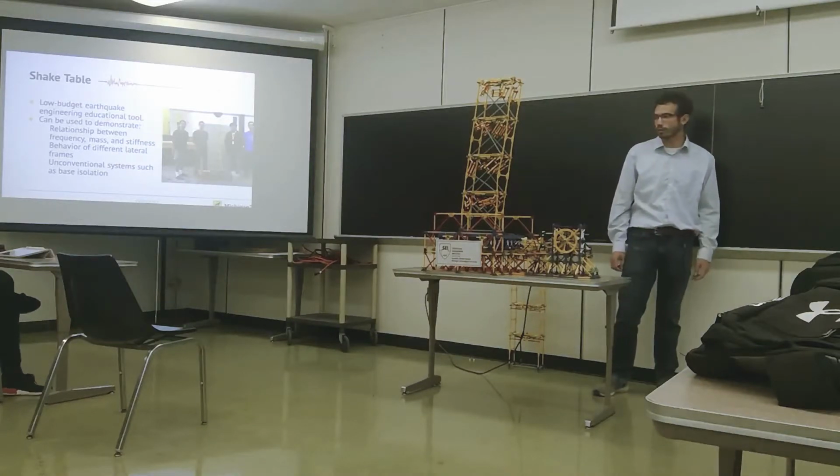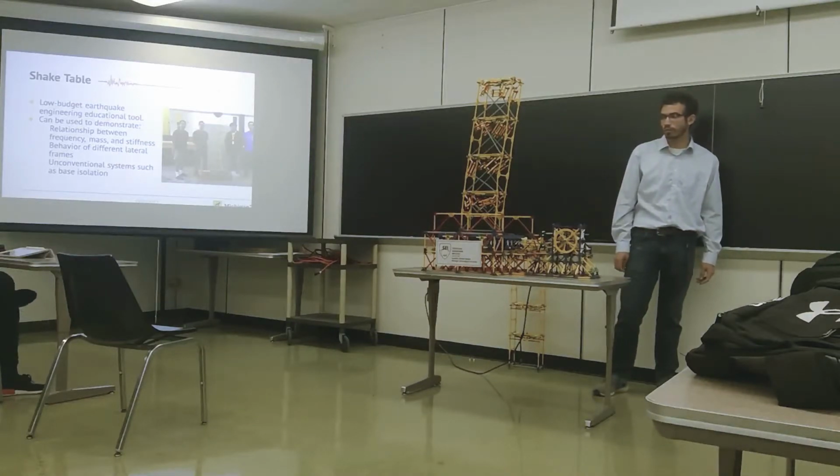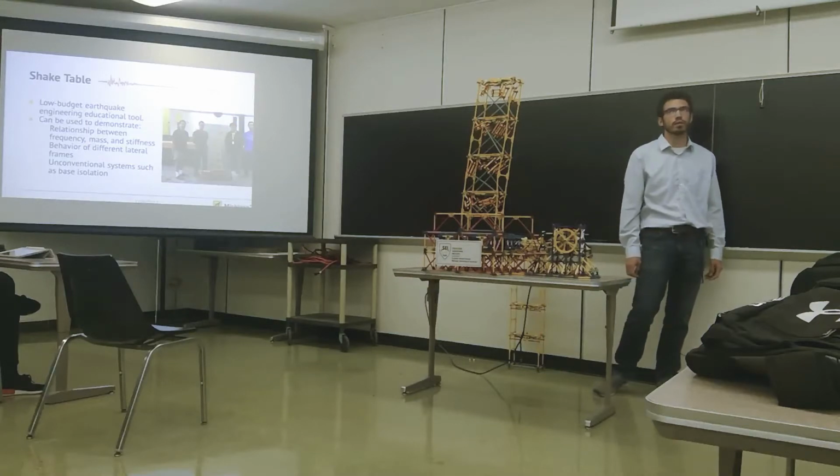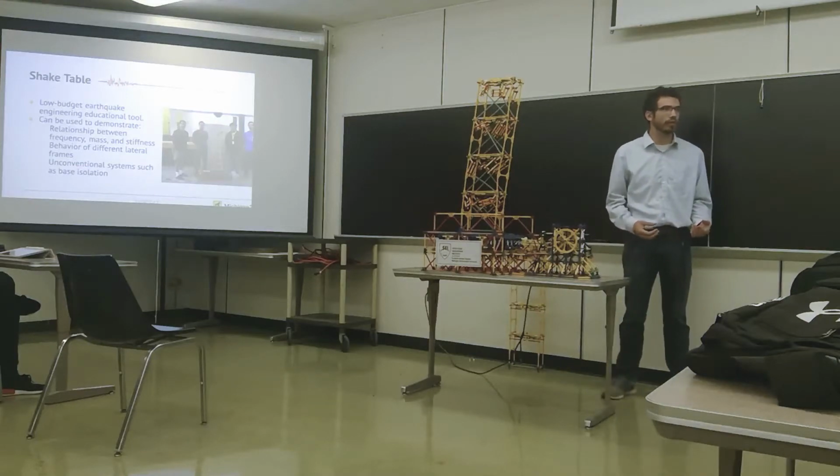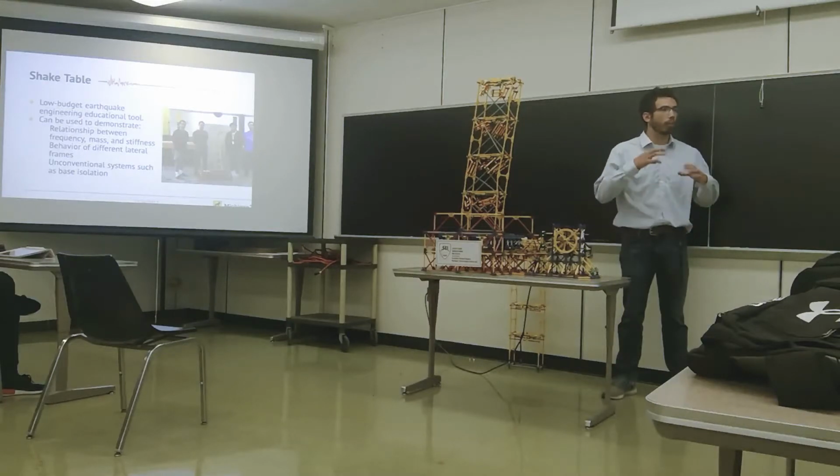So, if a building is damaged, will its natural frequency always become lower? Yes, unless there'd have to be something weird. Generally, damaged means your stiffness is decreased. The only thing I could think of is if you had a part that was meant to move that got seized up.